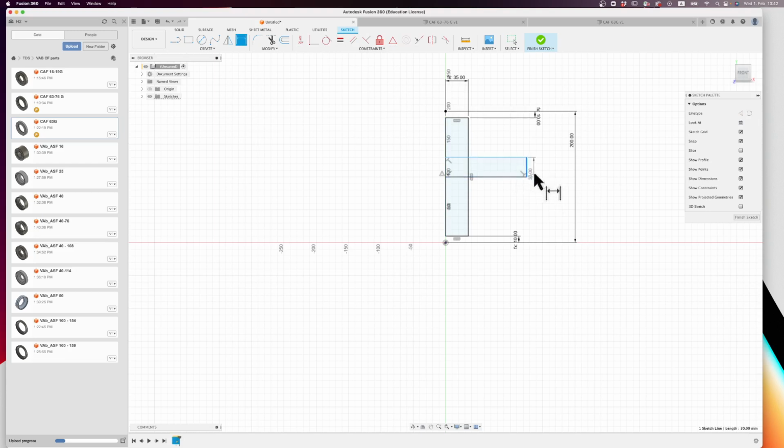And so here we're going to have our CF63 flange offset. So we can put a certain distance on here, and now we can obviously pick from where we want the distance to be, but let's just assume it's from the middle, and we can make that maybe 100 millimeters. So now we would have a flange that pokes out by 100 millimeters.